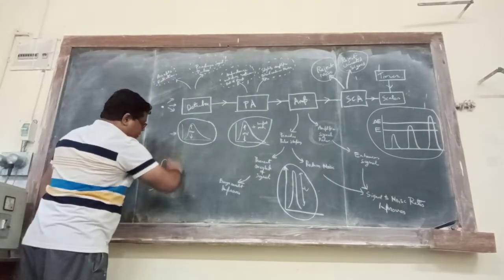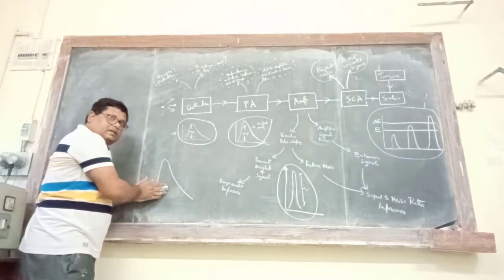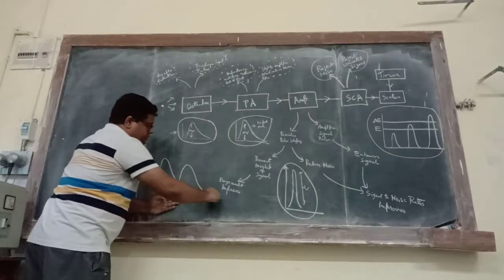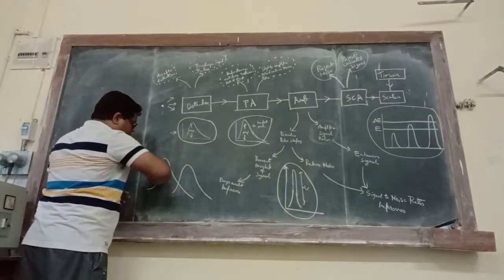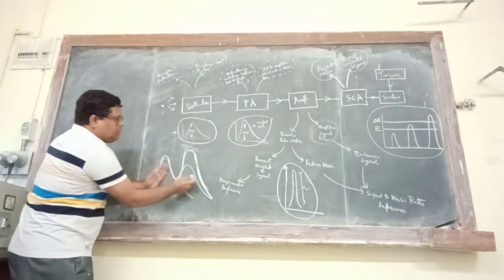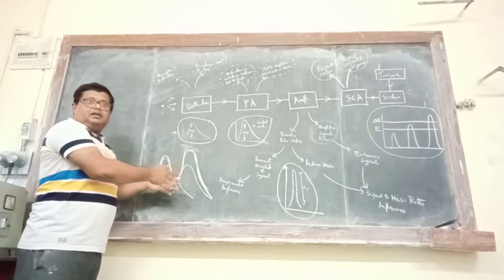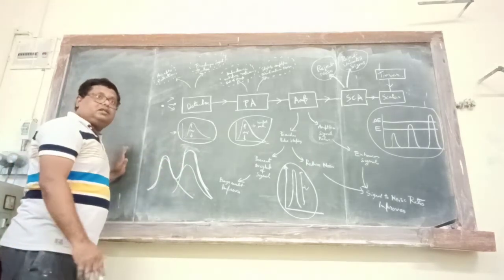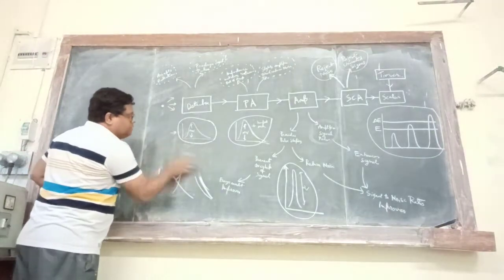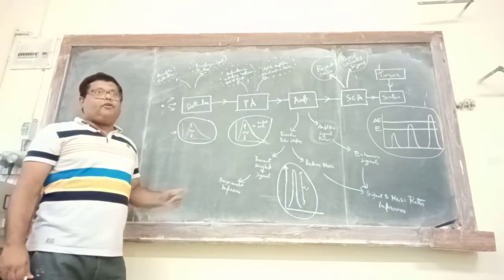So what can happen is that some radiation interacts with the detector, as a result of this we have a pulse, and immediately after some time another signal is there. So what will happen is we will observe something like this. You see, this is the overlap pulse, and as a result the entire energy information carried by the signal is distorted. It doesn't match that of the original radiation. So we must avoid the pulse overlap, and shaping is a very proper way to avoid this pulse overlap.